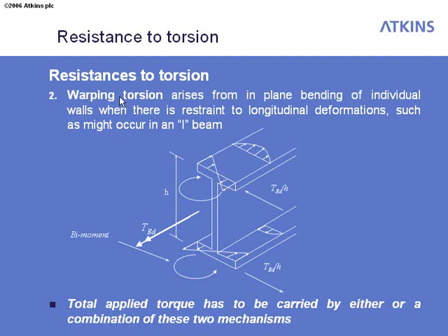It doesn't have to be the exact elastic distribution, but as long as the torsion can be carried by a summation of the mechanisms of the flanges bending sideways and the closed flow of torsion around the section, then that's a legitimate design.